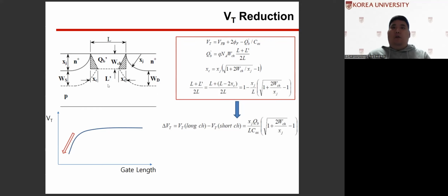Before we move on, we have learned about threshold voltage reduction in device physics. The deeper the junction, the more the diffusion region is enlarged. Because of the further diffusion region, the threshold voltage is lowered, which worsens the subthreshold swing even further.